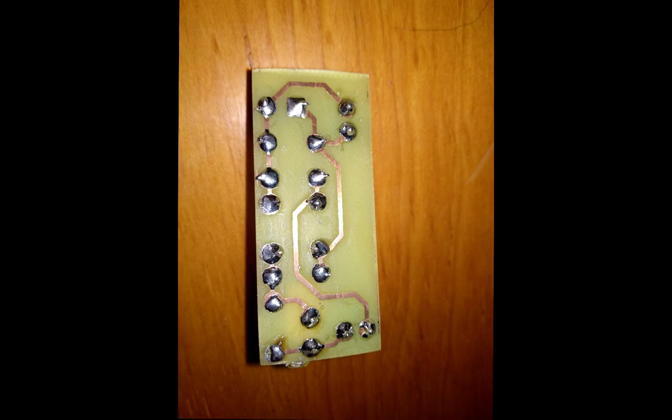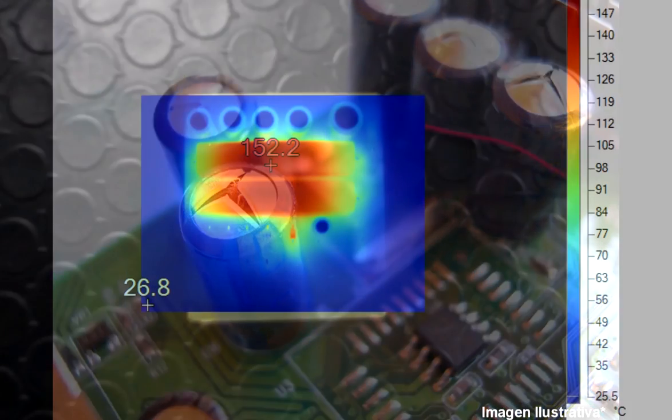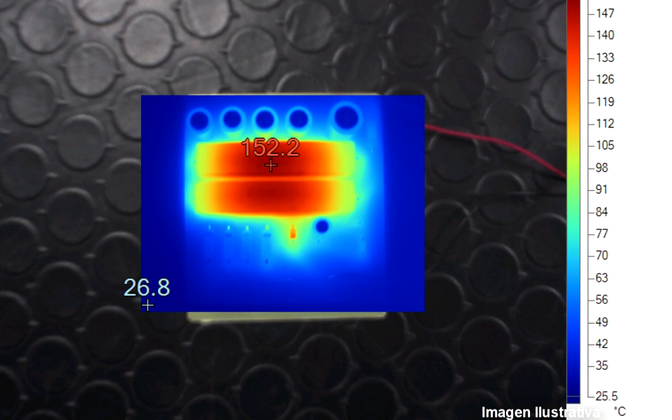As a conclusion, the team agreed that taking care of every single connection is important. Not verifying the electric power of an element could turn into a very dangerous situation, and even more in our design, because we implemented an electrolytic capacitor, and if an element is burning, it could modify the current direction and explode the capacitor. Also, verifying the heat of every element is important. If the board can't handle a certain temperature, it won't work properly.